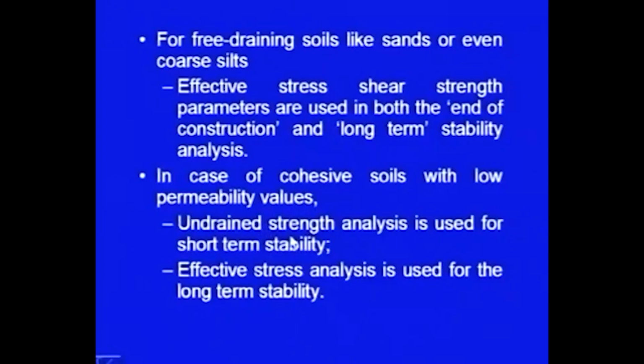So, undrained strength analysis is used for short term stability, meaning just at the end of the construction period the pore water pressure will be there, and undrained strength has to be used, because we should use that method which truly reflects the field situation. So, here the condition will be an undrained situation.